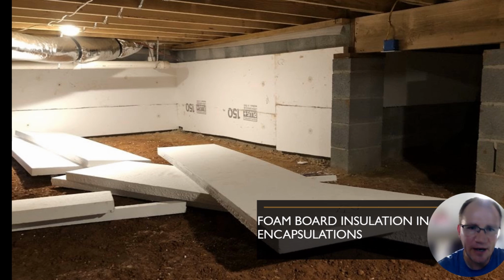One issue you may need to resolve when doing an encapsulation is, will you need to add foam board insulation to the exterior walls, or is it currently there? Let's say that it was currently there. One of the things you may need to do is cut that gap with like a 1 block path there to be able to do termite inspections, as you see here.